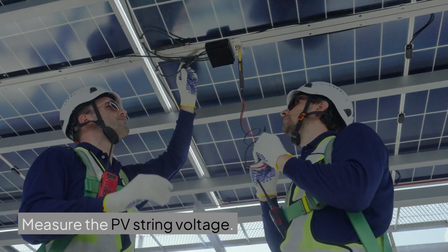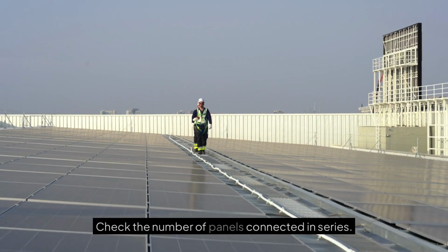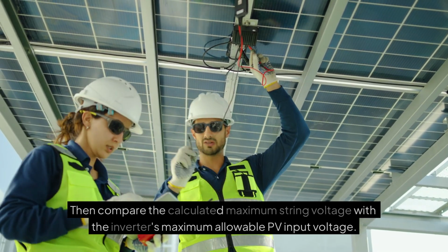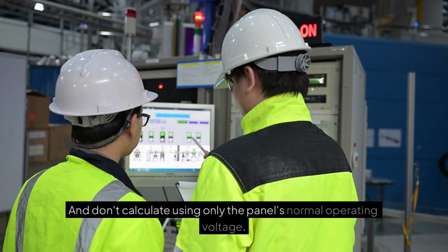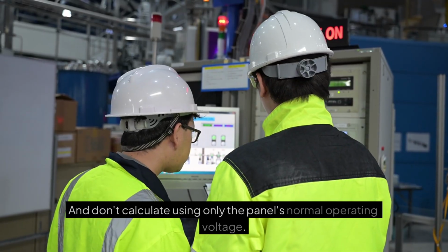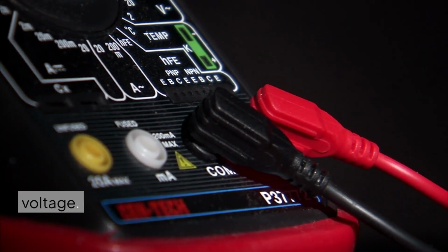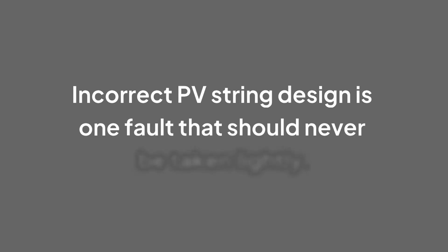Troubleshooting. Measure the PV string voltage. Check the number of panels connected in series. Then compare the calculated maximum string voltage with the inverter's maximum allowable PV input voltage. And don't calculate using only the panel's normal operating voltage. You must consider the open circuit voltage and the effect of low temperature on PV voltage. Incorrect PV string design is one fault that should never be taken lightly.